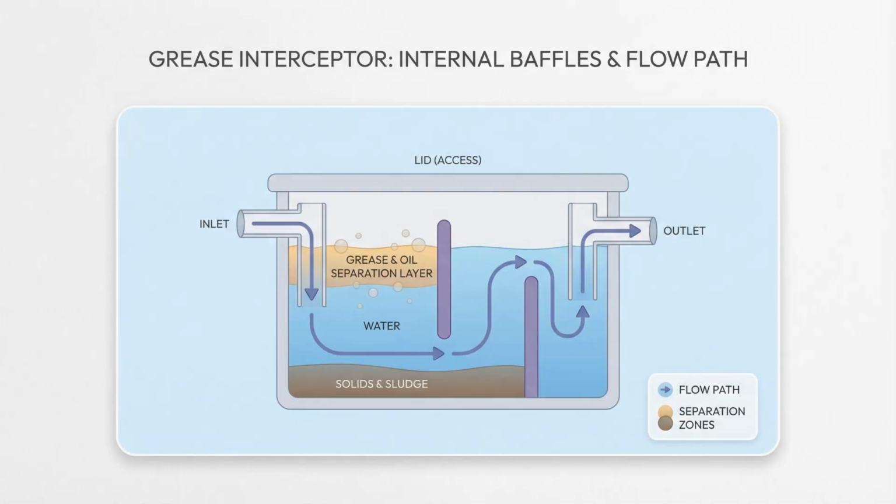Another vital component in commercial kitchens is the grease interceptor. This device captures grease from liquid waste before it enters the drainage system, preventing costly blockages. Sizing a grease interceptor correctly is essential and depends on factors like fixture drainage period and the volume of wastewater.